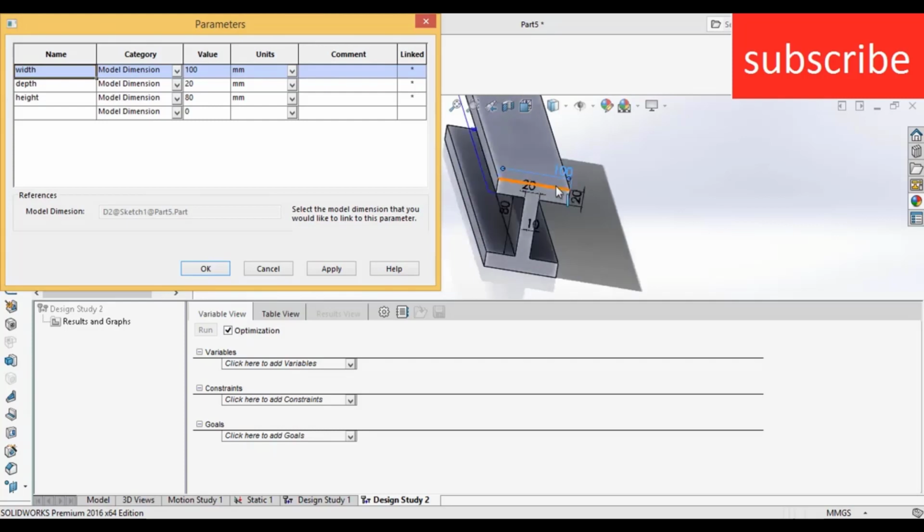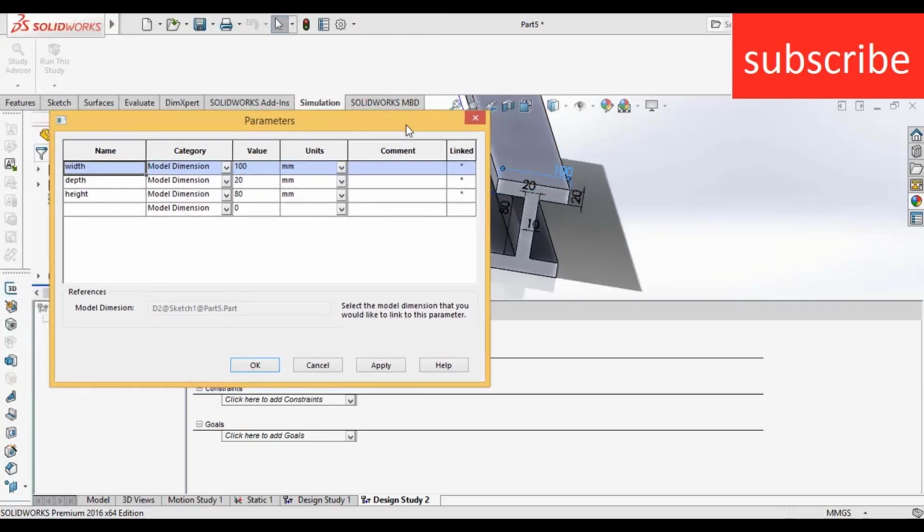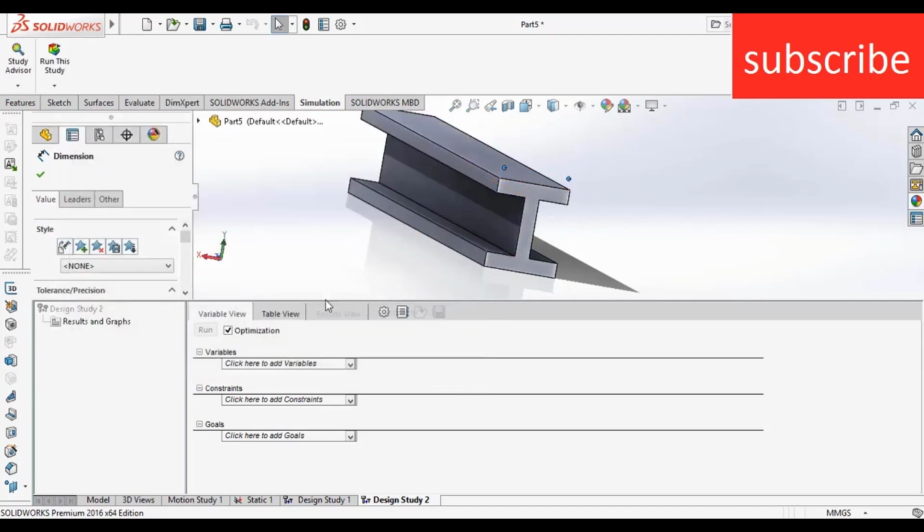Here I already selected the parameters, so let me tell you what the parameters are. A parameter is something that we are going to vary so that I get a good factor of safety or stress at a lower mass. So let's add a parameter from the sketch.